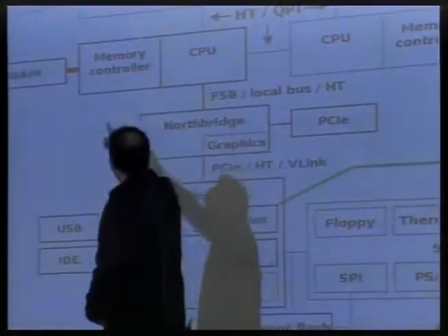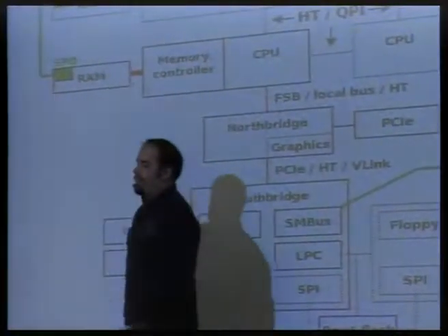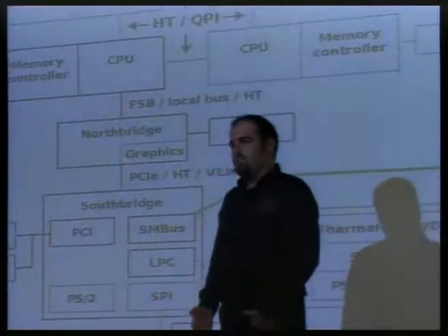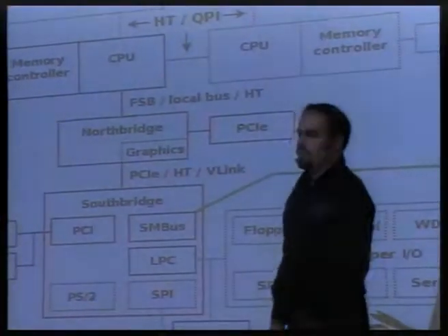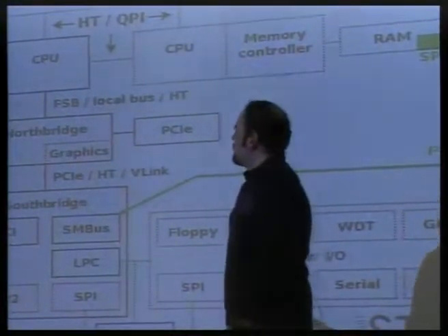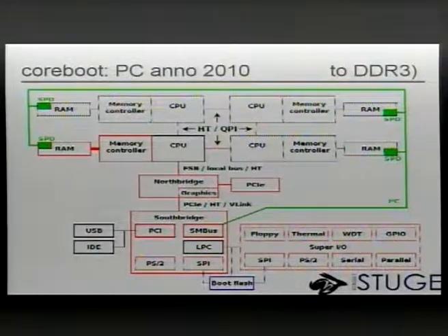But the red stuff, by far the most interesting challenge is this memory controller guy here, because this thick red line is getting a lot of development. It started out with the RAM chips being connected directly to the CPU, and now we have DDR3. I haven't read enough about that, but DDR2 at least is running so quickly that in order to do the memory controller initialization, you have to use a brute force search to find the correct timing adjustments that the memory controller is going to use when it's talking to the RAM module, the DIMM, to compensate for how the mainboard was designed and how the tracks are laid out on the board. So that's a lot of fun, and it's getting really complex.